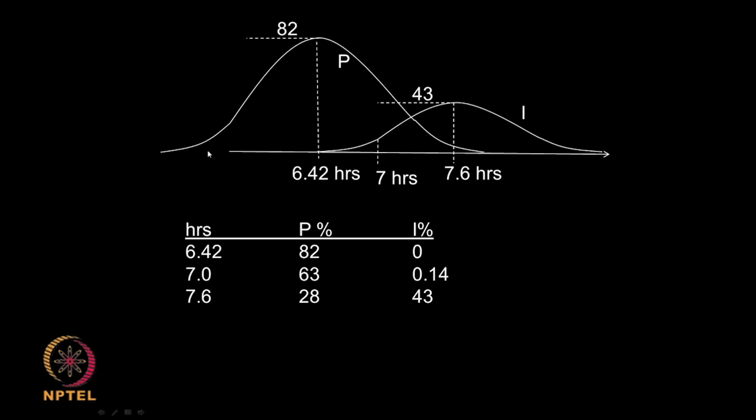Okay. So, you have the product and generally these impurities overlap. Life is not so easy that the product peak and the impurity peak are far away, that whatever you collect will be 100% pure, no. So, if you are collecting sample up to this, there will not be any impurity, but if you are collecting beyond this, some impurity will keep coming. You see this, okay? And you cannot just collect up to this because your yield of the product will be low. So, you need to strike a balance.